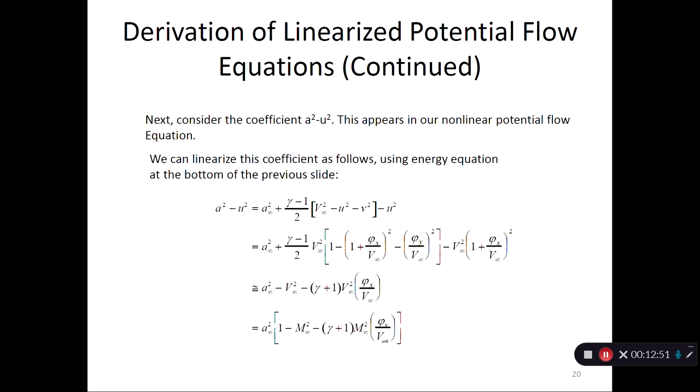We could normally throw it away in very low subsonic flow when Mach number is very much less than 1, so that this difference is very, very large. We can do it in supersonic flow when Mach number is very high, because this number is very large. But in transonic flow, Mach number is close to 1, so this is a small number, these two combination. This is a small number, so we have to keep the entire enchilada. So we can't neglect one over the other.